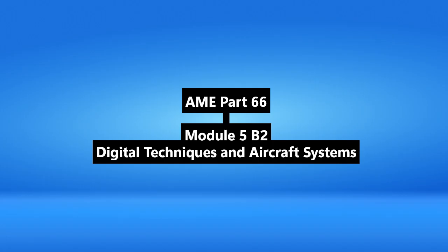And the module mentions passive matrix versus active matrix LCDs. What's the important difference for flight decks? Performance, mainly. Passive matrix uses a simpler grid to address pixels. It's cheaper, but can be slow to respond, have lower contrast, maybe some ghosting.